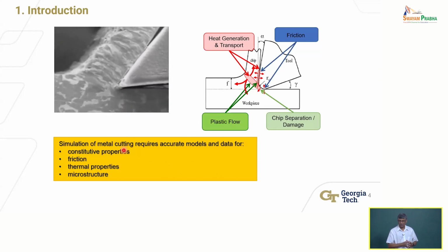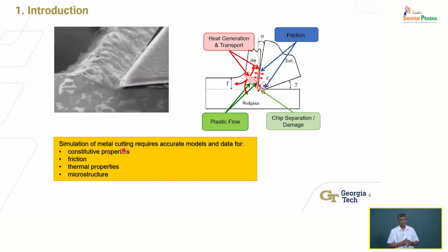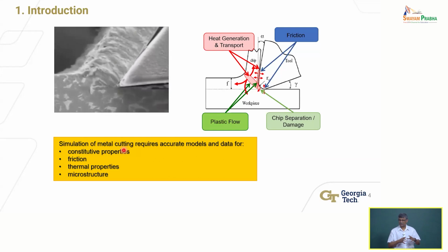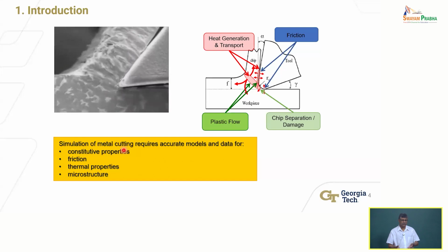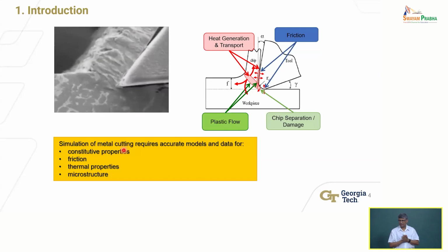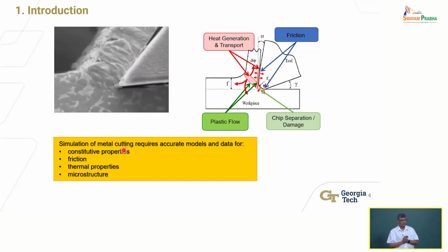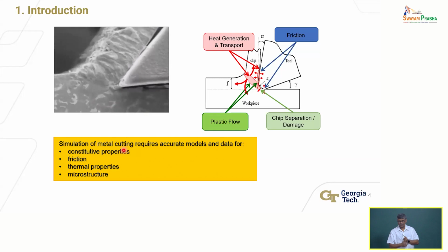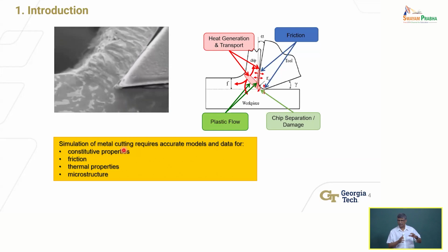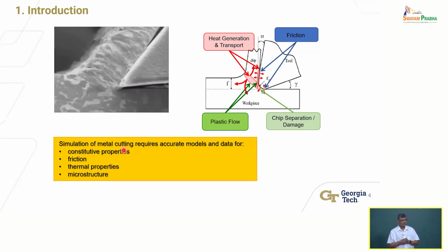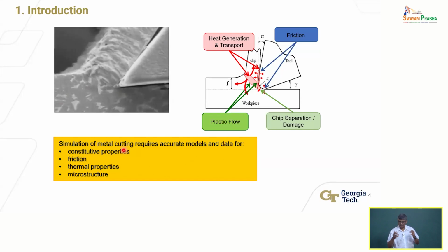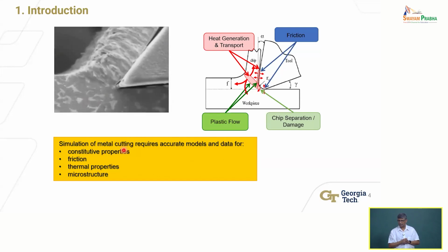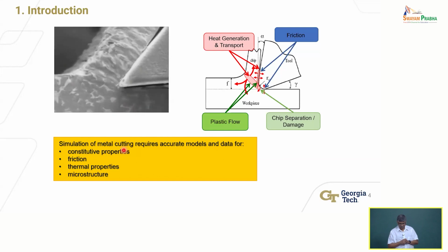That's because you used a very aggressive cutting condition, or you're cutting some very difficult to cut material. Over 95% of the mechanical energy that is being expended in a metal cutting process is converted to heat. Energy is conserved, but it's converted to heat, and that is what causes the chip to glow, depending on how aggressively you cut.